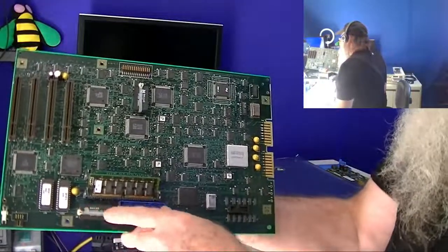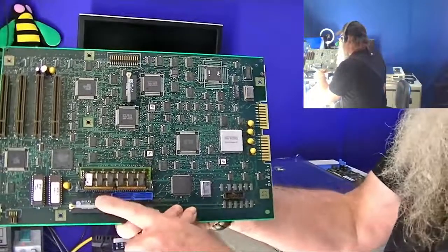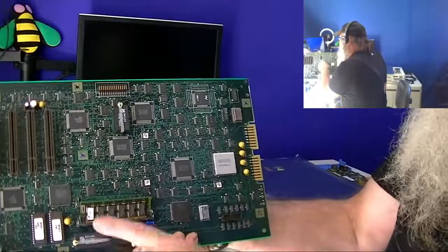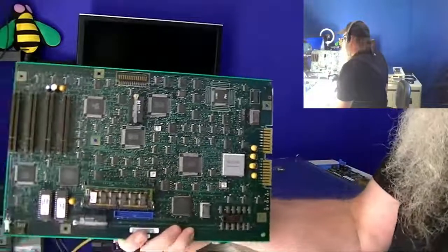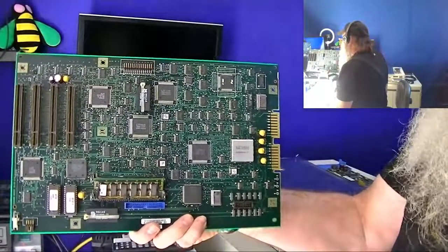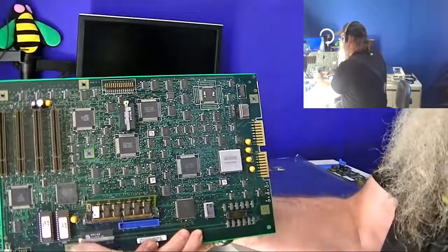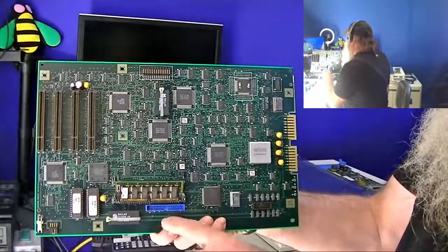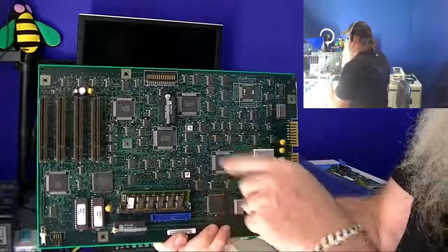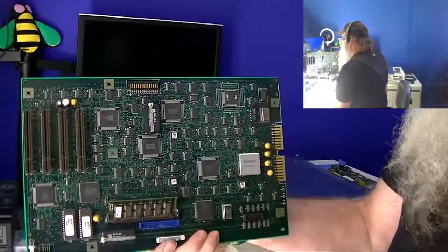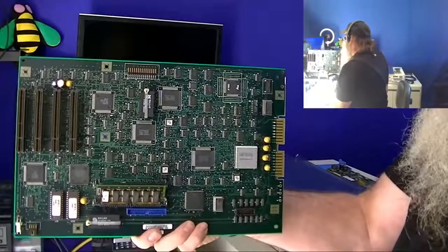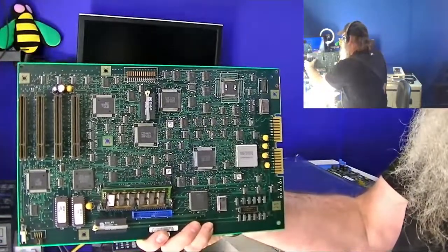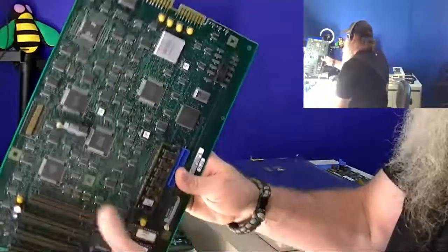The DS1225 modules. I've got some DS1220 modules, but if these are somewhat sketchy, and I don't even know for this particular planer, this may not have been used before. There may not have been anything there that really taxed these batteries. So it's almost like they have a shelf life, and may actually still have enough of a charge to be halfway functional. But I'll have to look at replacing those to get equipment that's truly operational and won't crap out on me.